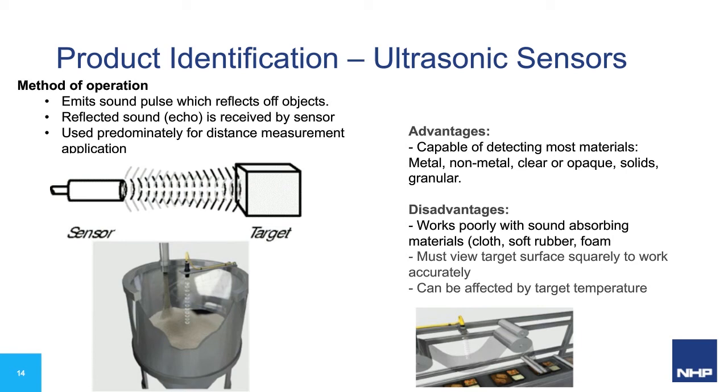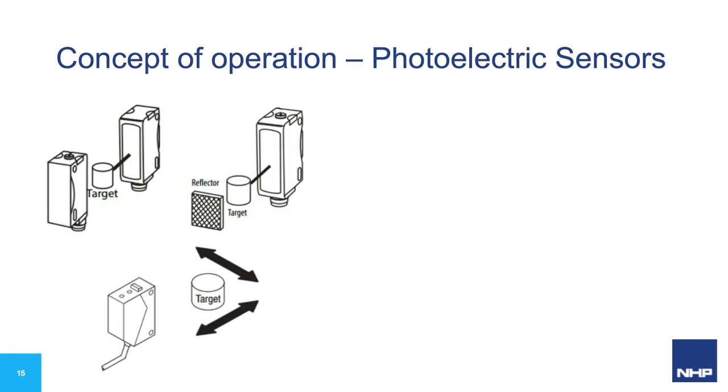Now, moving on to the last device we will cover, we have photoelectric sensors. So these can be used in high precision, fast detection and measurement situations where you cannot or do not want to touch the object being sensed, and you do need to have some distance between the sensor and the object. So photoelectric sensors emit their own light as the detection medium, and there's 3 different types which operate differently to each other, with some of these having their own subtypes.